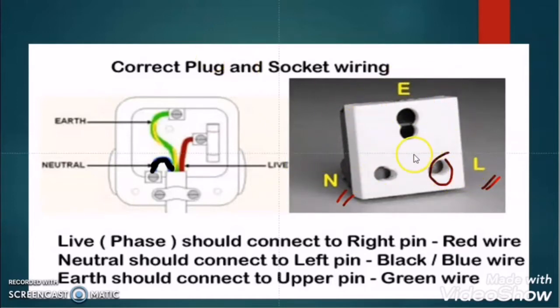If you try to remember such tricky things, you will forget after 10 days, 20 days, or 1 month, 2 years. That is why you should always build your own shortcut. For example, in my engineering life I learned that a capacitor acts as an open circuit for DC, so I remember the word CODE. I did my engineering 8 years ago, but I still know this because of that code. And I know that an inductor is a short circuit for DC, ISD. So I will always remember it throughout my life, and never confuse which one is open for DC or for AC.